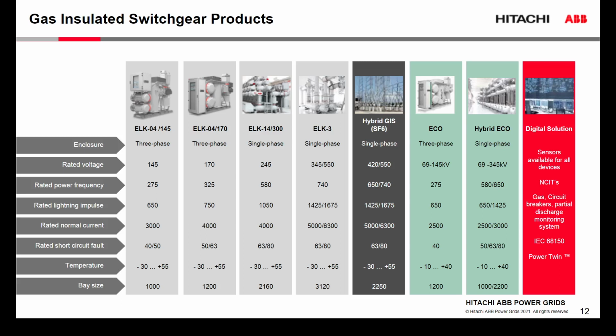Monitoring systems are used, meaning gas monitoring, circuit breaker monitoring, partial discharge monitoring systems, which can be used within the GIS. You are capable of interconnecting that equipment with 61850 to the overall SCADA system and create with that a digital system utilizing the GIS technology, similarly to how you would do for conventional substations.